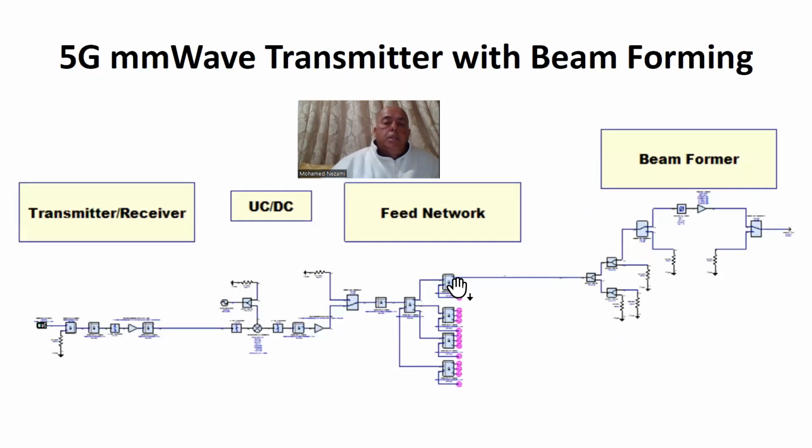So we're going to replace this signal generator that we used to test the entire chain with a real modulated 5G signal and do co-simulation. Co-simulation means you can take an RF chain and a digital signal processing chain, put them together and co-simulate, and actually trace the signal throughout the entire chain from bits to beamformer output at the antenna feed point.